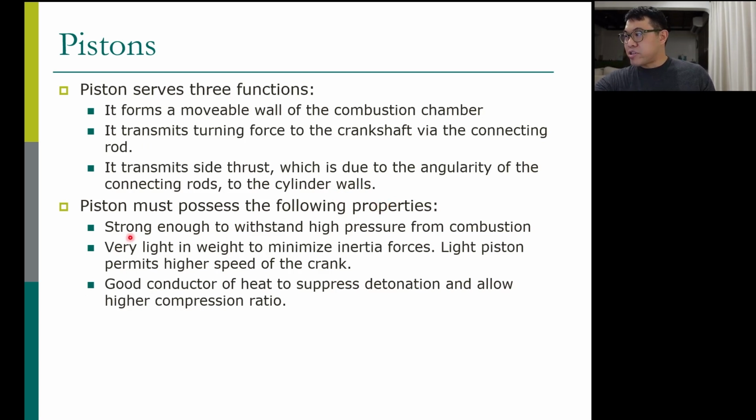First, it has to be strong enough to withstand high pressure from the combustion. Second, it has to be very light because it has to move fast, to minimize inertia force. When you minimize the inertia, it moves faster. A light piston permits higher speed of the engine. When your engine has higher speed, you have more power.